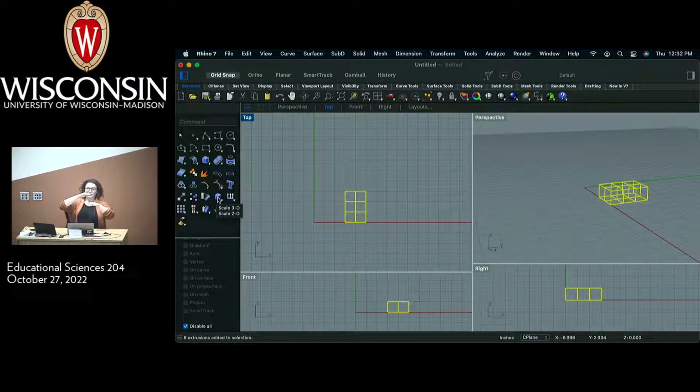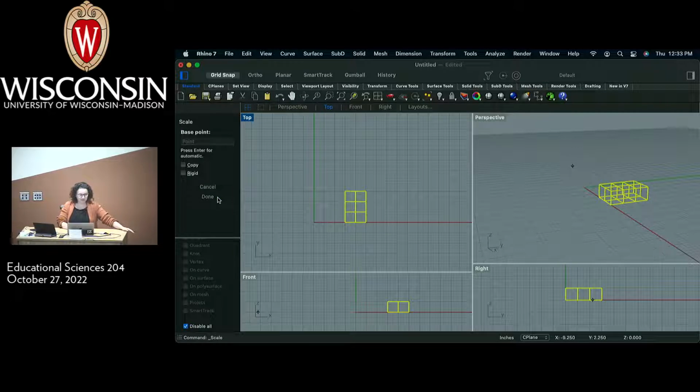I want to make myself a little bit taller, but keep everything else the same, you know? That's a non-uniform scale. And so there's all sorts of other ways that you can scale things so that it's not just one-to-one. But for 95% of the reasons why you would want to scale stuff, scale 3D should work. So that's just a left click here.